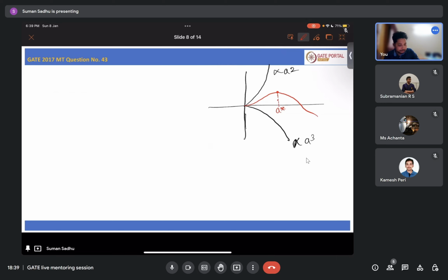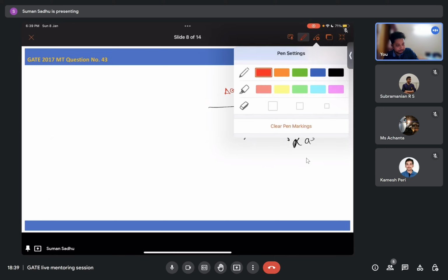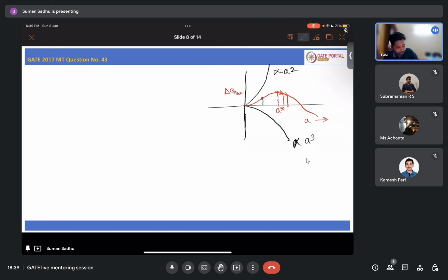You can see that if you add one more atom here, the resultant delta G homogeneous will decrease further. That means after this it is stable. If you are somewhere here, and you add one more atom, your free energy, delta G for homogeneous, is increasing. That means this is not stable. Only after this point it is stable. So basically this is the maxima of this curve.